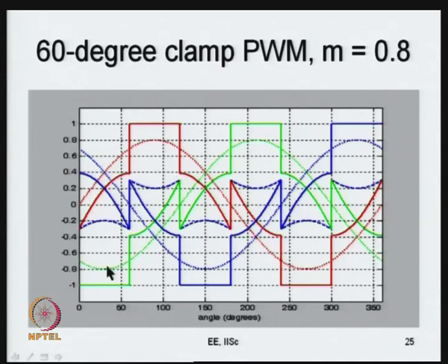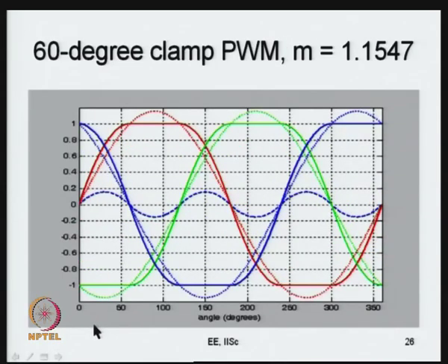All the 3 modulating signals are also phase shifted versions of one another. This is a kind of bus clamping that ensures equal loading of all the devices that we were discussing in the single phase case now. So this is 60 degree clamping now. We will discuss this in greater detail in the next lecture, where we will essentially deal with clamping, but just let us familiarize ourselves with various kinds of thing.